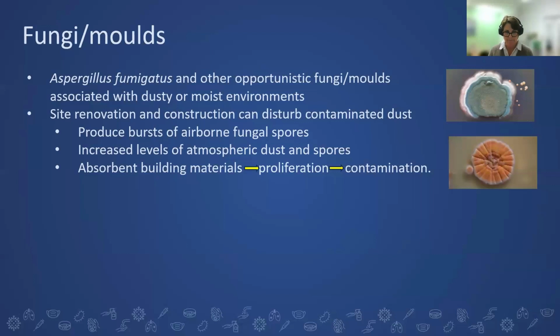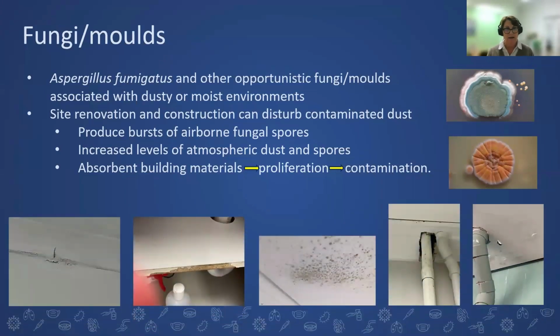your practice building. So we know that the presence of Aspergillus species in a healthcare facility is a substantial extrinsic risk factor, particularly for those patients who are very immunosuppressed and may be at risk of invasive aspergillosis. So improperly functioning ventilation systems, such as air filters, your air filter frames, window air conditioners, false ceilings, any fireproofing material that you may have, damp wood materials, or even ornamental plants, can all actually be nice reservoirs for these